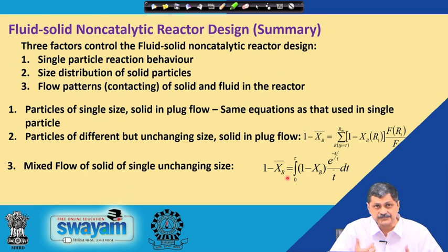We have learned that 3 factors predominantly control such design, and we have considered 3 cases. One is particles of single size, solid is in plug flow, and then second one particles of different but unchanging size, solid is in plug flow, and third one is particles are in mixed flow, but having single unchanging size.